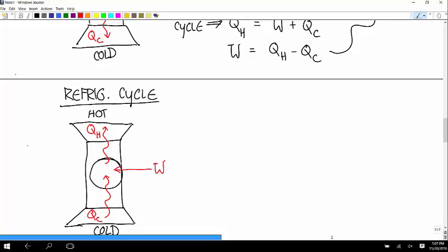In the case of refrigeration cycle, you use a compressor to compress the refrigerant, raise it to a higher temperature, then hold that up to the coils in the back of the refrigerator. Heat energy goes out, then you let it expand again, and the temperature goes back below the temperature it was at before.